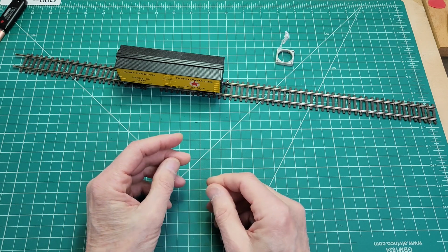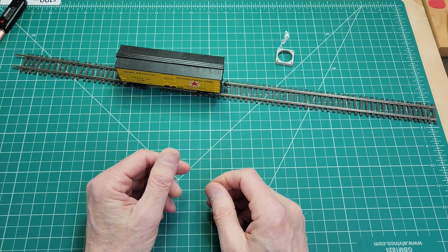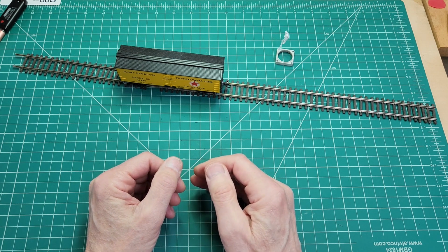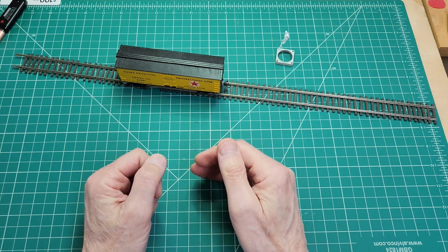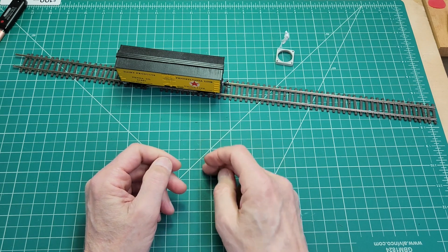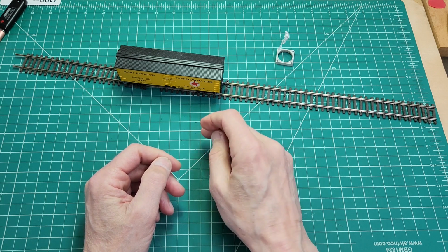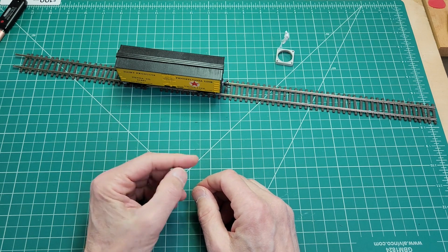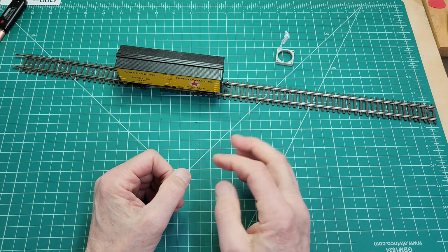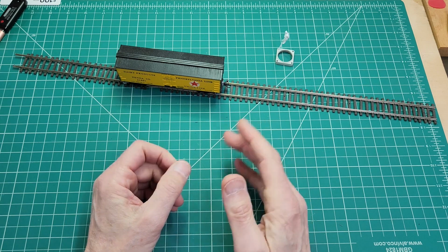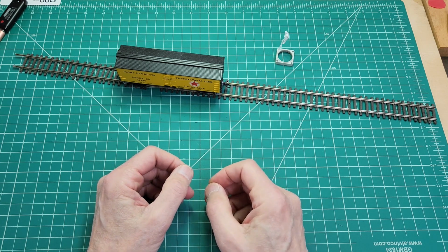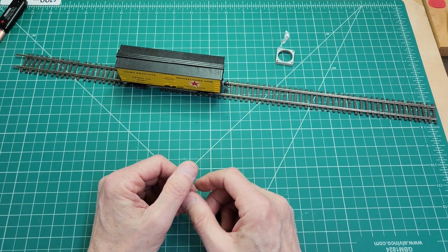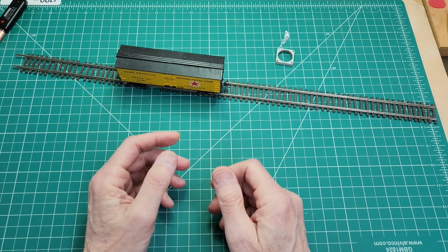So I took a little study to figure out that the library, as it connects with an attached device, nulls out all of the endpoints except for 0. So all that information for the driver, in this case talking to device number 1, doesn't exist. And so it's necessary for the init function to create all that information. So as I just said, every attached device has an address number.